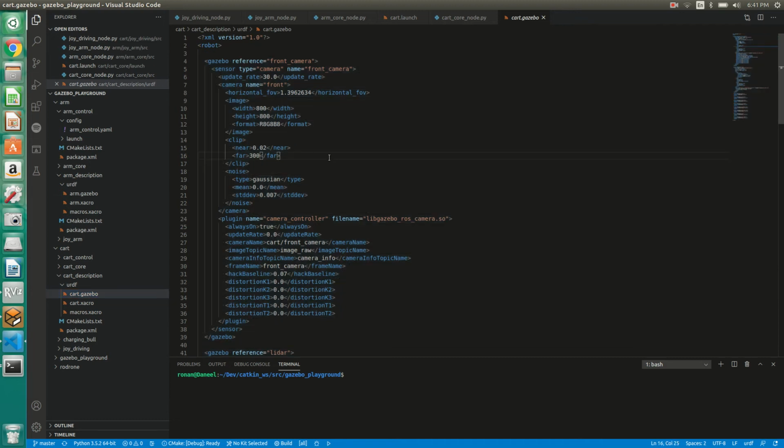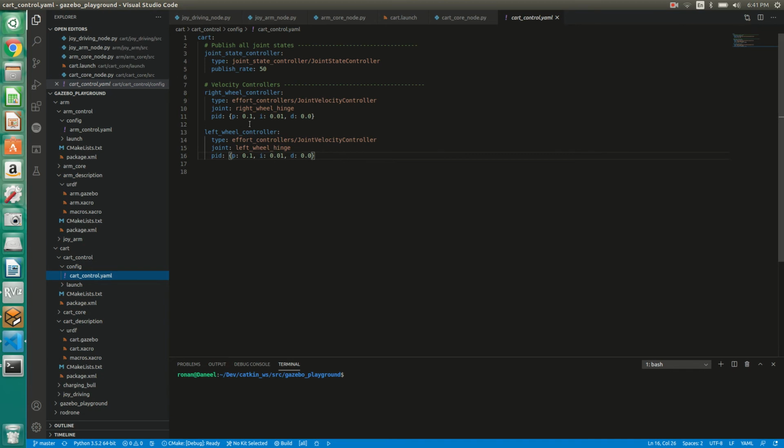And then I also specify the joints at the wheels and the controllers at the wheels, which are just the motors turning the wheels. Now these controllers are meant to emulate the way a DC motor or stepper motor or any other kind of motor would control wheels in the real world. So they're emulated using PID controllers in the virtual environment. And right now I've just given these PID values in this file here that are just to emulate how motors would behave, and these should be tuned at a later date, but this config file I have open here shows those values for the automobile.